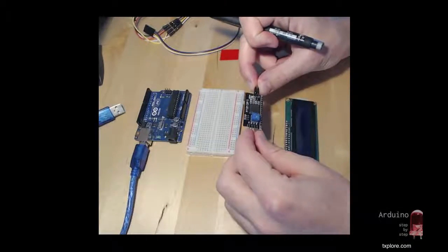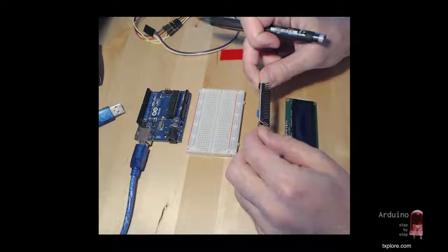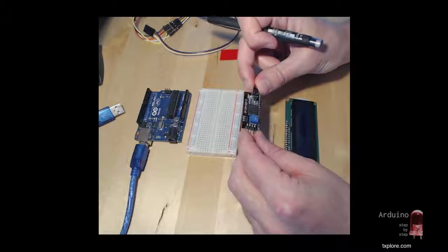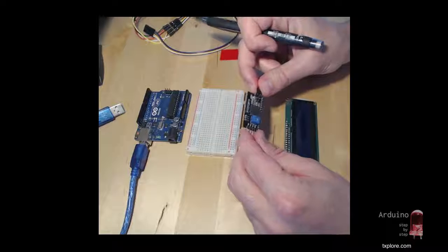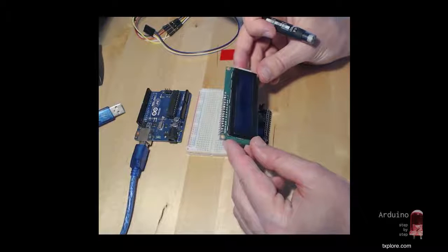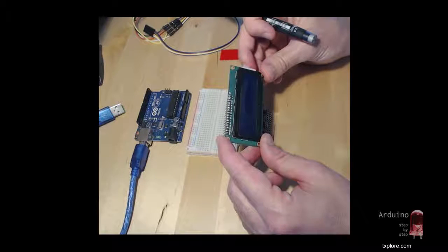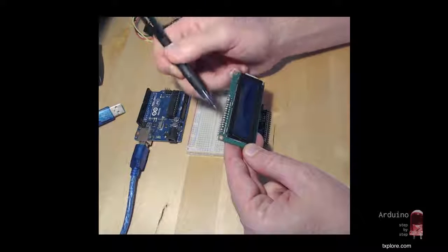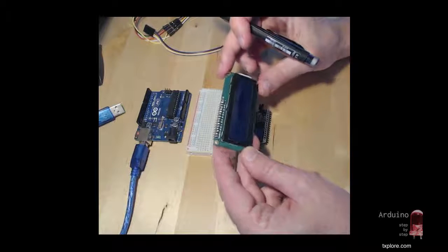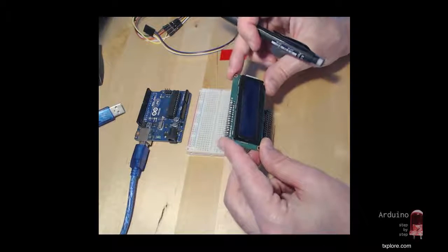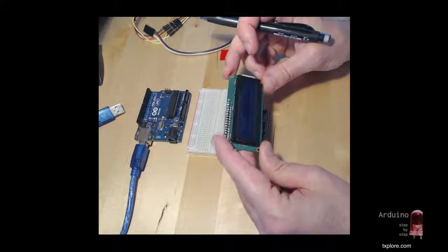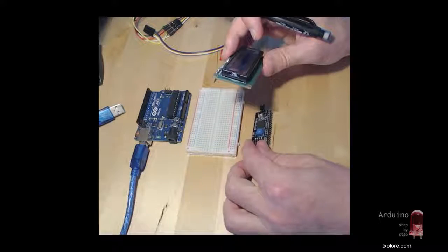In this first demo, we'll have a look at the parallel to serial adapter using the I2C interface. This little device here is what's making it possible to go from parallel to serial. You may remember in lecture 24 when we connected this LCD screen directly in parallel mode into the Arduino, and we were using back then these digital pins to carry the data. We used 4 of the digital pins, so we used the 4-bit parallel mode. Still, there were too many pins to worry about. We also had to power the backlit of the LCD. Just too much wiring to worry about.